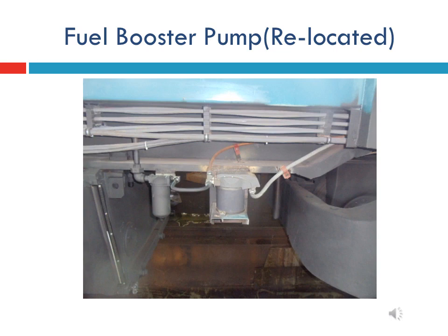Fuel booster pump relocated. Through this slide, I want to say that in most of HHP locomotive, the fuel booster pump is shifted to underframe in between fuel tank and bogies. It has been done by DLW under modification because of frequent failure of inverter of motor. Further, DLW clarified that there was an issue of net positive suction head of pump with motor, so modification has been made.